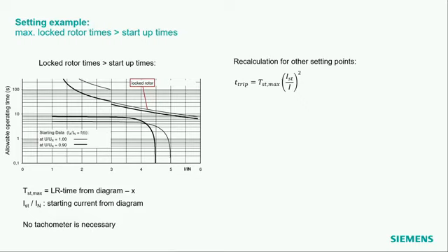So the I square, I divided by I square function, that means if the current is smaller, then the tripping time is longer. And this curve here behaves relatively close to that formula. So this is a fine finding, and it shows it works here.